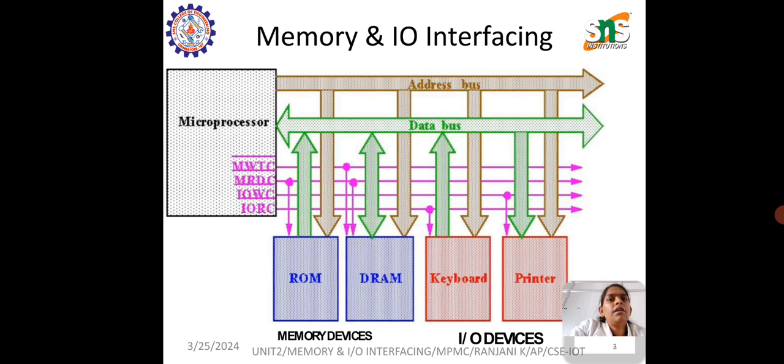So in the 8085, A15 to A8 are the pins of the higher address bus, AD7 to AD0 is the pin configuration for the lower address bus and data bus, and ALU is the arithmetic logic unit. Then there are the read operation, write operation, and ready signals.